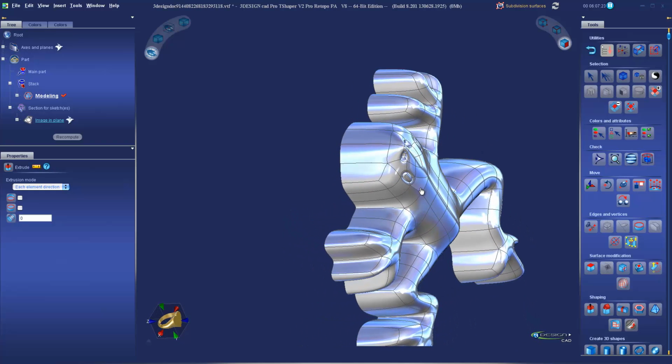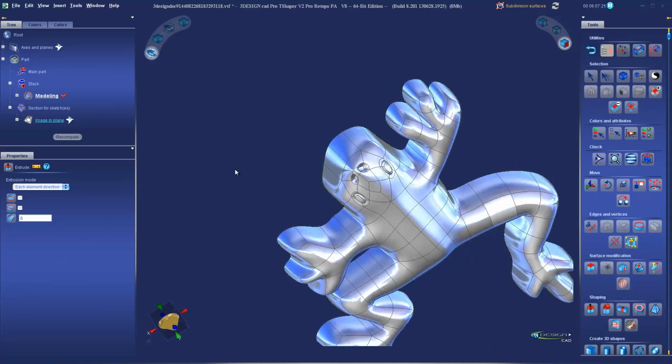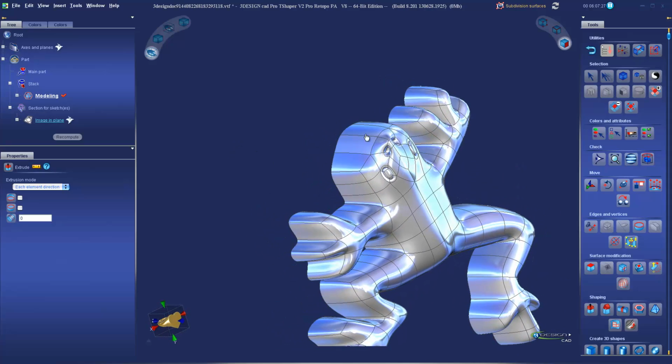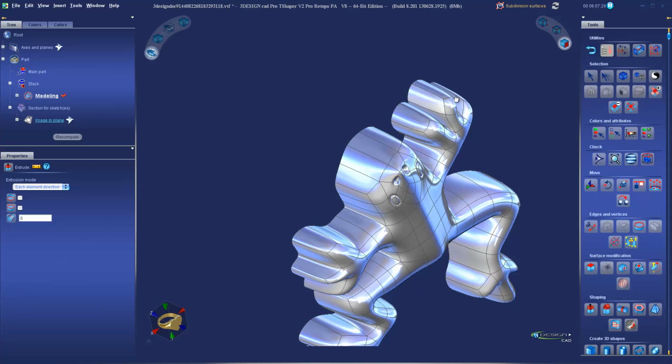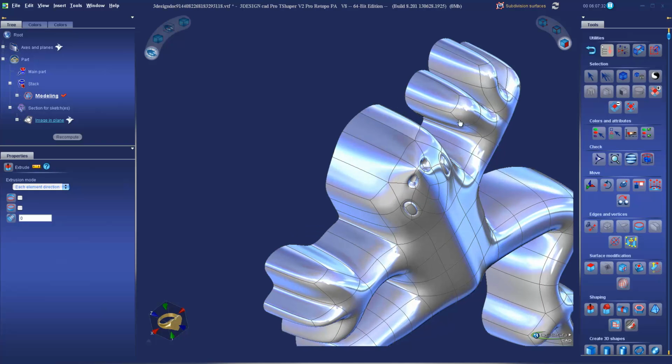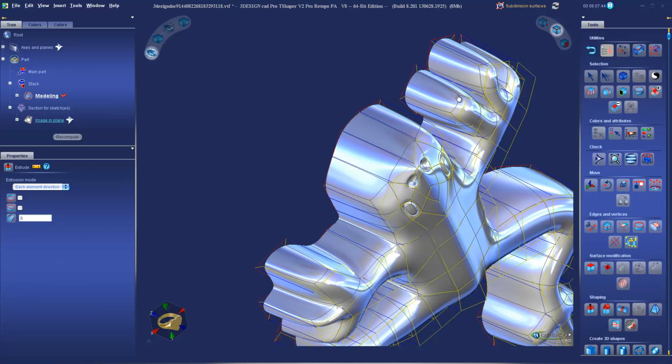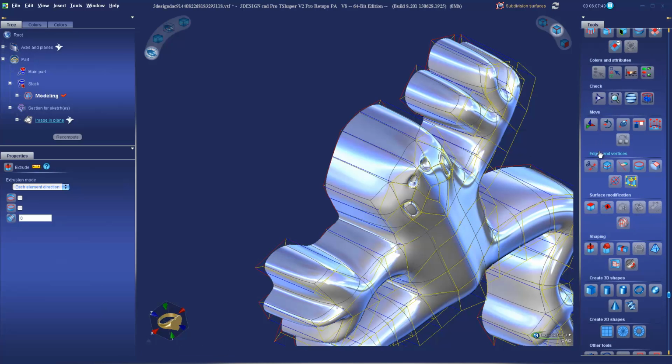Okay, so next up we want to add a bail to this piece, and to do that we're going to put it across here, but we don't have enough polygons here to separate that bail from the rest of the faces. So we're going to subdivide this. To do that, I'm going to do a ring selection. So I'm just going to select one edge going in this direction and do an edge ring. It's going to select that entire ring all the way around the piece.